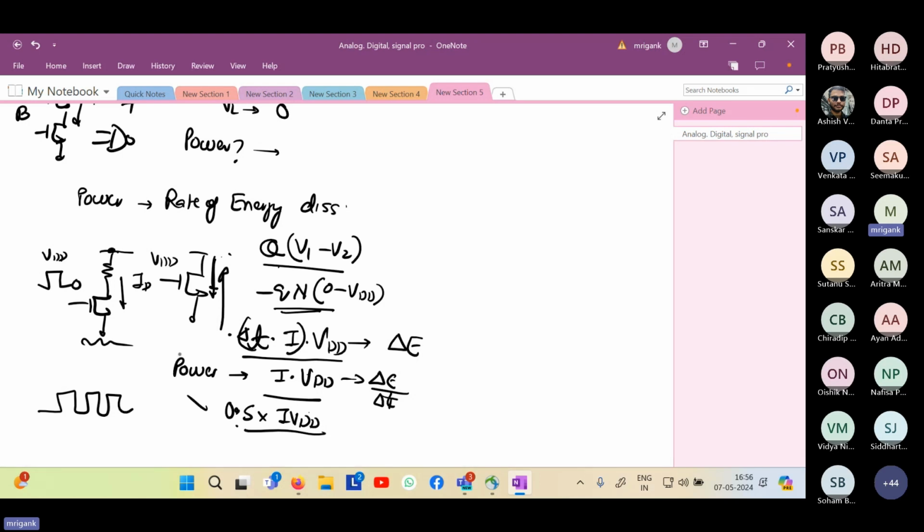Likewise, most of the analog circuits, amplifier, differential amplifier, common source amplifier, all the amplifiers that you have seen, will have some static biasing current. All of them work with some biasing current because we are biasing the circuits at a high gain region, right? So we are choosing some bias point, and this requires some ID for which it is biased. Therefore, all the circuits will consume that static power all the time. This is called static power. Static because the average current is always flowing, and as a result, that power dissipation is always happening.